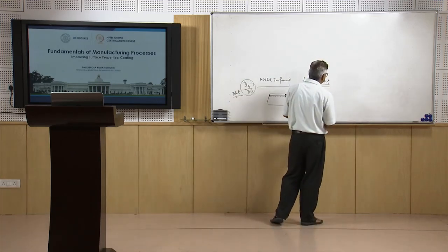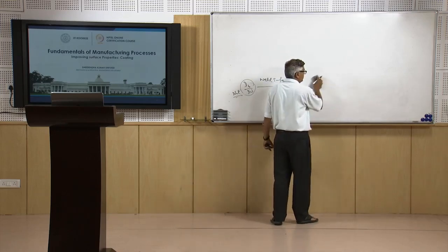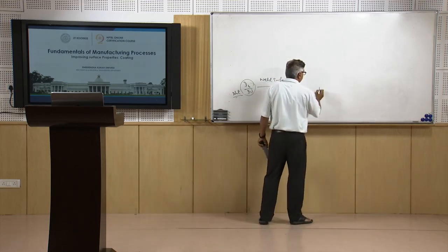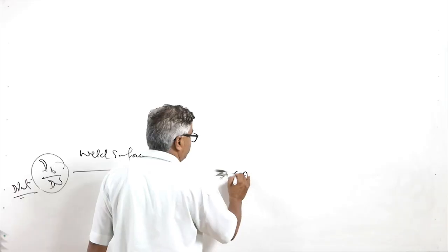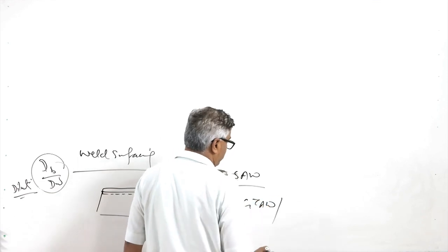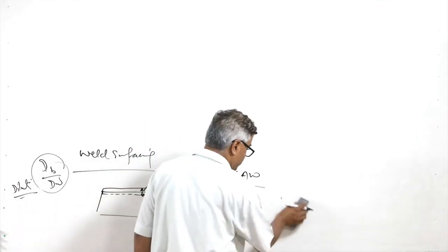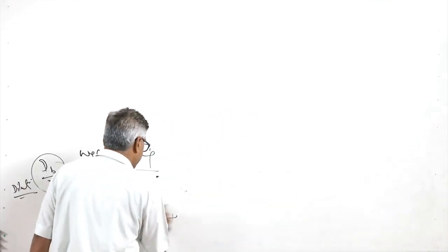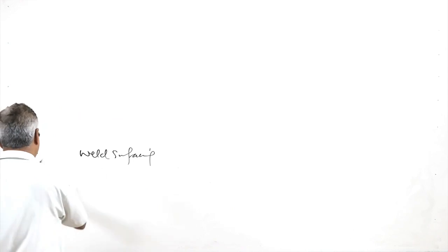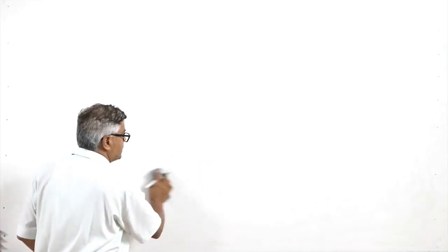High energy density facilitates the melting of the coating material and limited melting of the base metal, leading to lesser dilution as compared to common welding processes. High dilution is encountered with processes like submerged arc welding as compared to GTAW, where filler is fed separately, because this process uses a non-consumable electrode. So, as per the kind of process we are using, the heat input and the cleanliness of the weld will be different in weld surfacing.